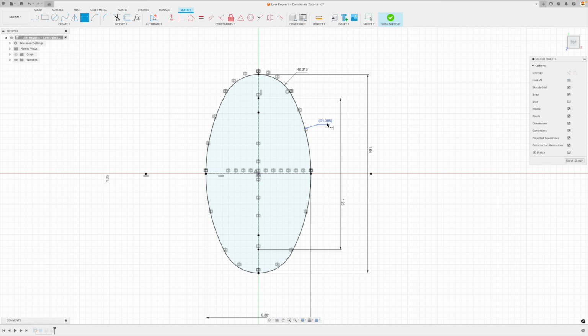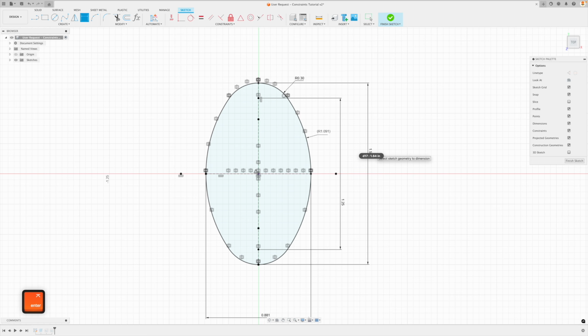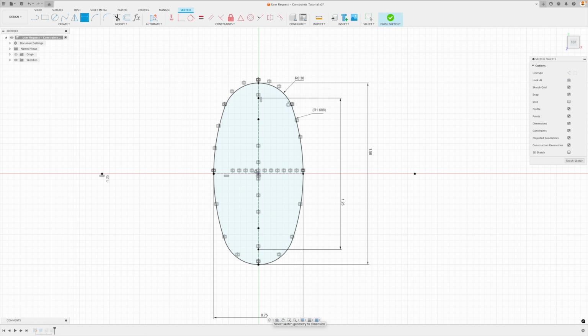Now here, this is very interesting because if we change anything else on our sketch, this will update. And so these are called driving dimensions. This one, our overall height, our width are all driving dimensions, and I'll prove it to you. I'm just going to change this to 0.3 and look at our driven dimension, our reference dimension. There we go. That automatically updates. I can change this as well to whatever I want, 1.5. There we go. So you can see that this updates constantly depending on the driving dimensions.